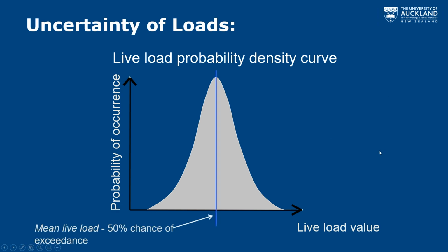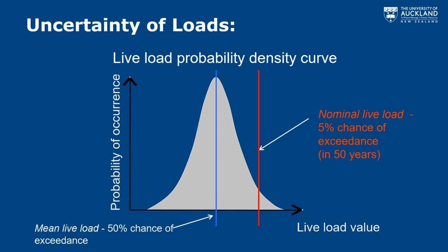So you might think, well, maybe we use the median value or the mean value. The only challenge with that is that, well, it means that half of the time we're going to have more load applied to the structure than what we would design it to take the capacity for. Because remember, we're always going to come up with the capacity of the structure based upon the loading which is there.